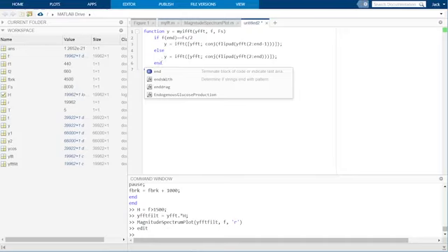The only reason these components are ever needed is in case y is a complex rather than a real-valued signal. In that case, these components are not generally equal to the complex conjugate of the first components. This situation involves mathematics that are beyond the scope of this course. For our purposes, we can just ensure our MATLAB IFFT function is exactly as demonstrated, and it will work for any real-valued signal.